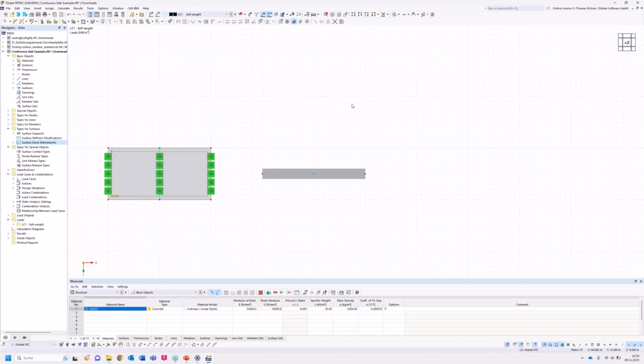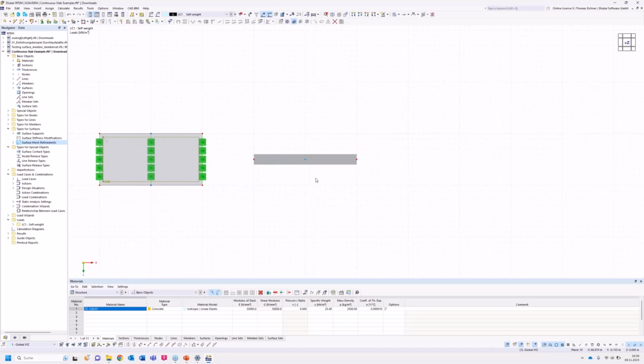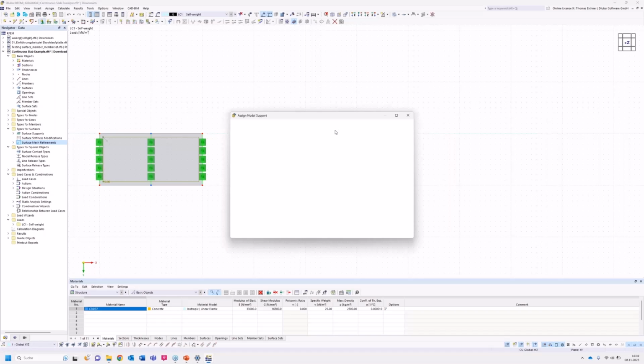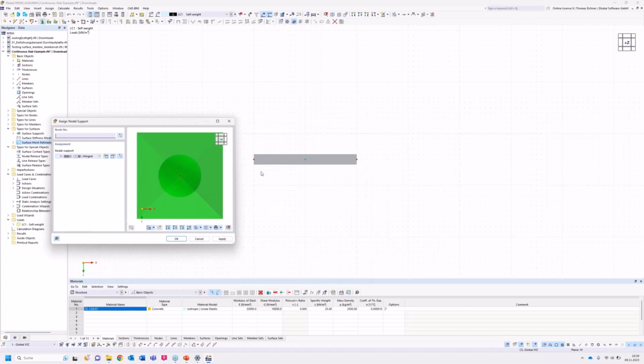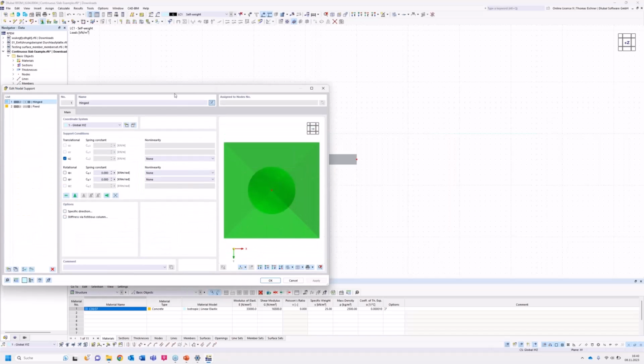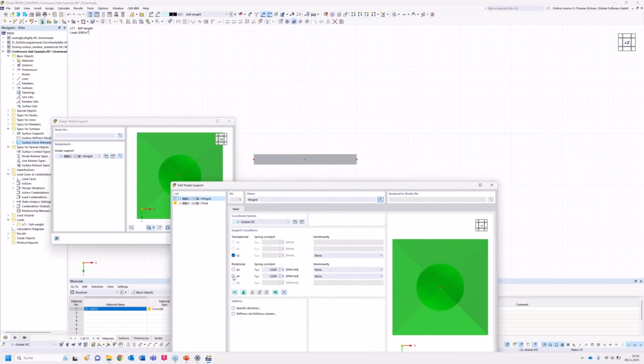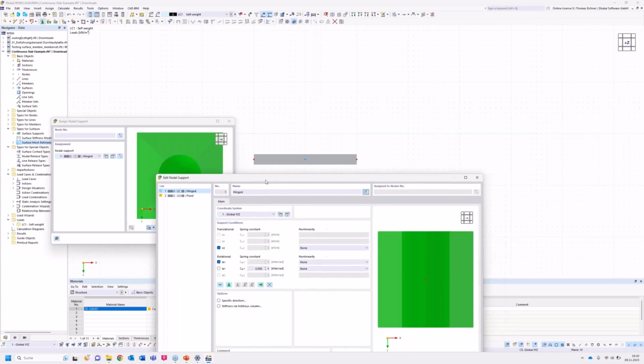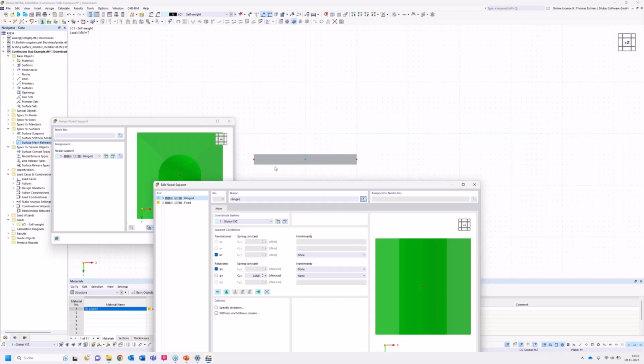Now we have this beam, we have our K matrix again. We can go for nodal supports now and add some supports to the system. One problem here is that we could use the hinged one, the predefined hinged one, but on the predefined hinged one, there's one degree of freedom which we need to block for beams, and it's the phi x. So it's the rotation about its own axis. If you didn't do it, it could just rotate and fall over.